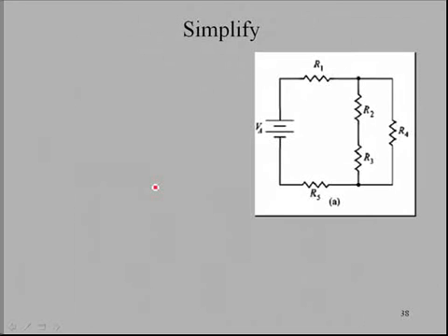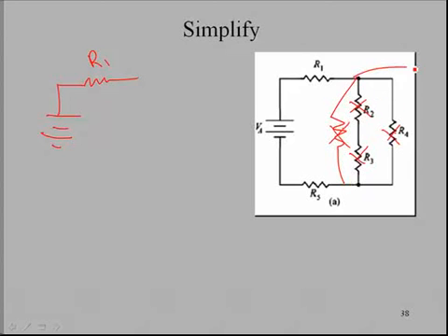Okay, here we have the first one. Let's see, here we have a power supply, and here we have R1, and then we have these components over here. Well, obviously R2 and R3, we could eliminate those, and that could be replaced by a single component, and then this replacement component and R4, those could be in parallel, so that would make a single component for here.